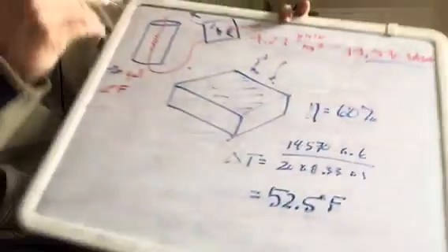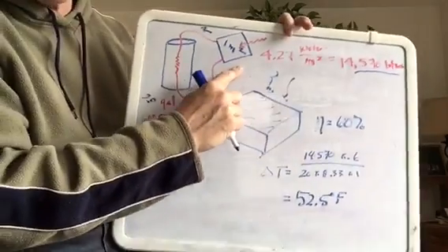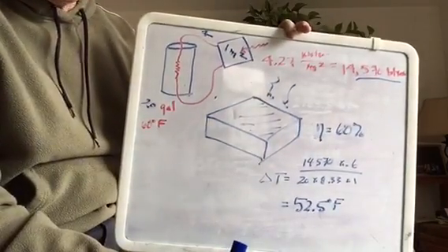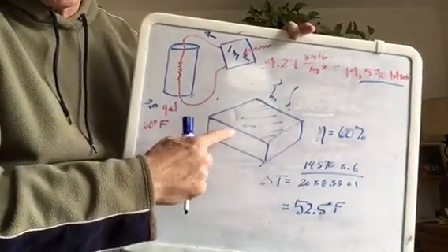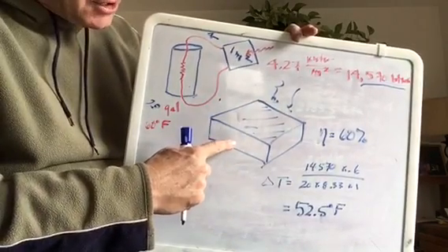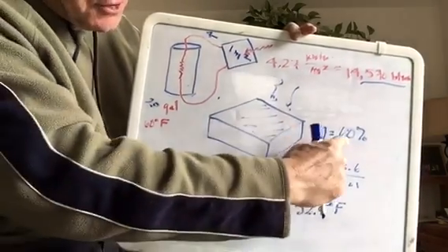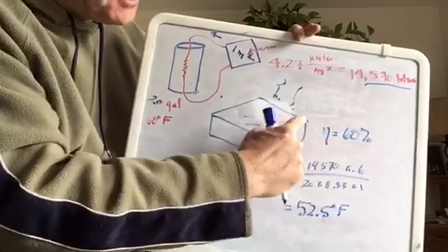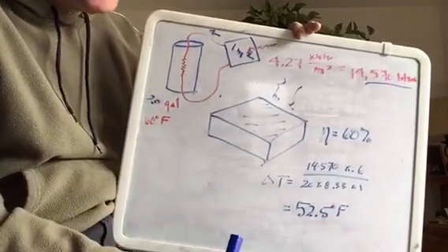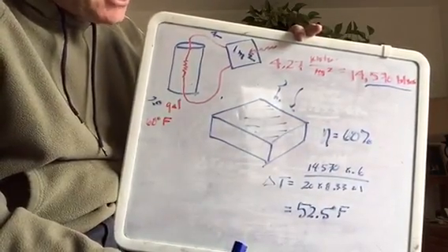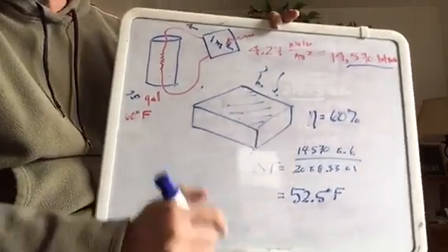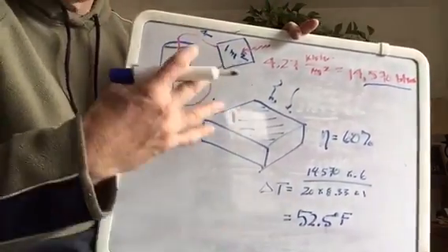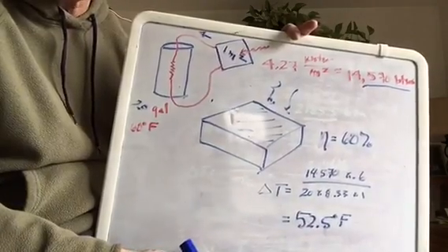So a meter squared, there's no way it's going to do it using PV. On the other hand, if we make this box that's a meter squared on top, and the top is coated with a surface that works well at absorbing solar, and in addition we minimize convective losses and emissive losses, then we can get a good delta T. All right, hey, there's a third option, and we'll save that for next lecture.